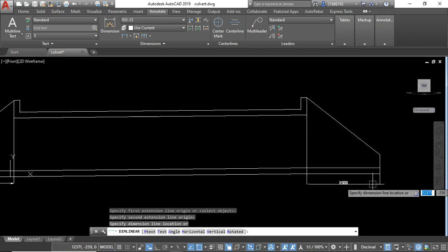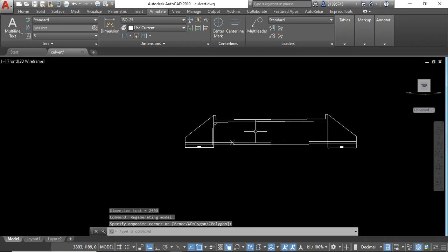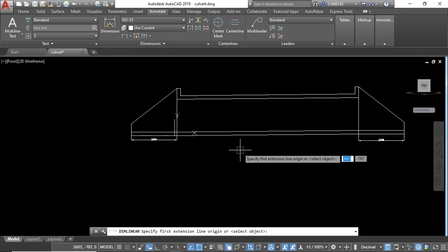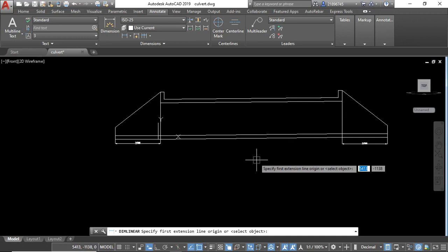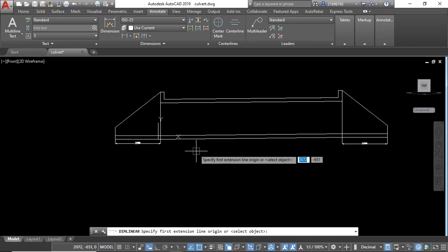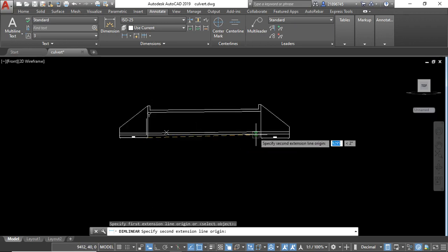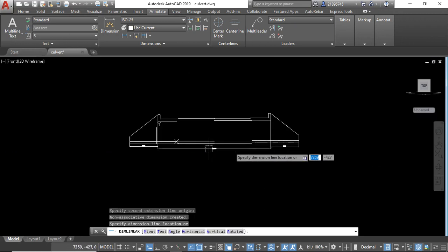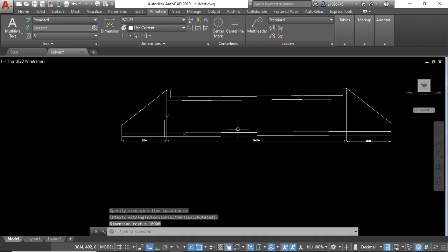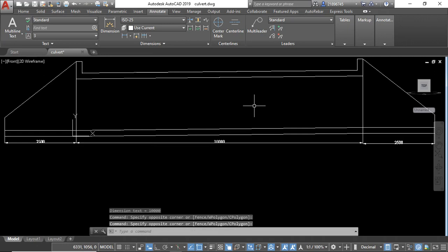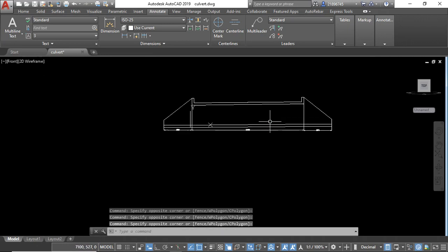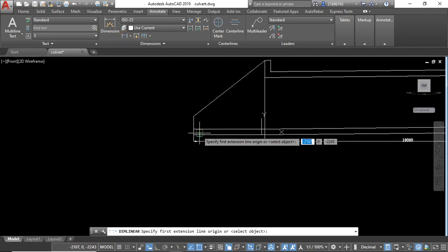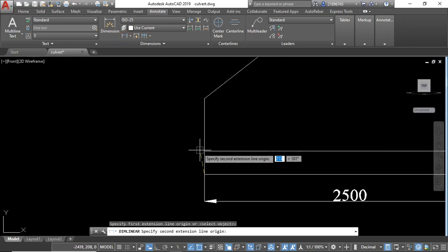So I want us to dimension in millimeters, although if you want to have it in context, like on the Civil 3D surface, you have to do it in meters, or even on survey plans, they are usually in meters. So it's just a matter of scaling back to meters, but this one I'm doing in millimeters for no other reason than clarity, and it will conform to a drawing as small as this one rather than having a 0.0 something. That would be a bit confusing for the people doing the fabrication of formwork and all that, because maybe they work in millimeters.